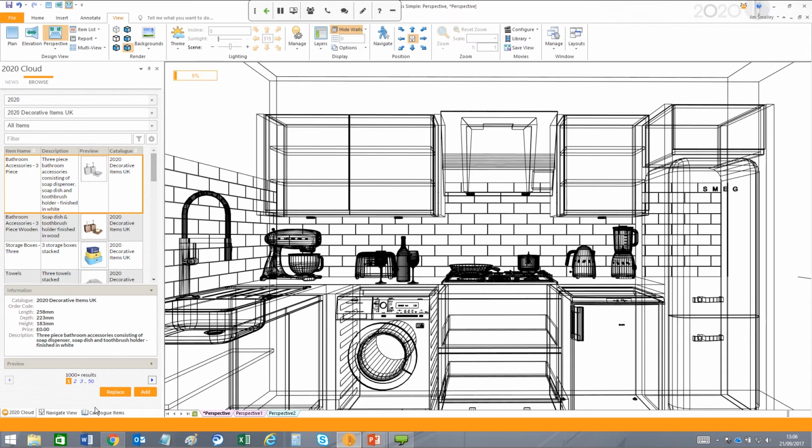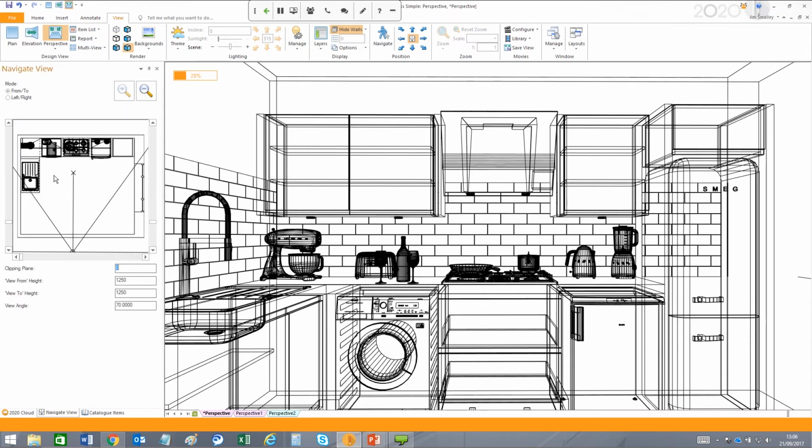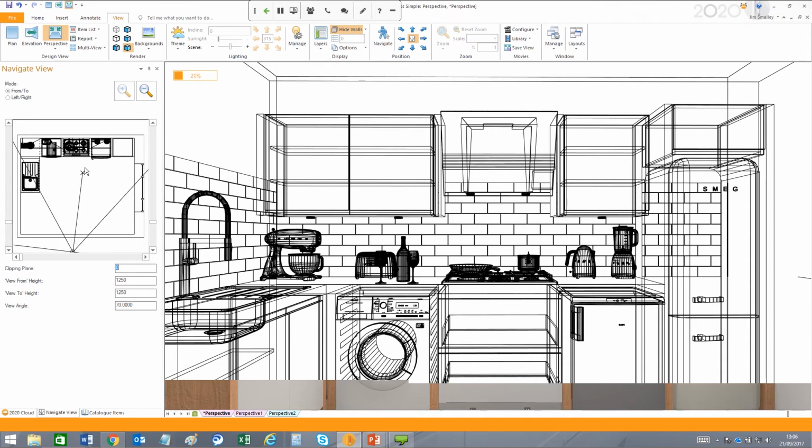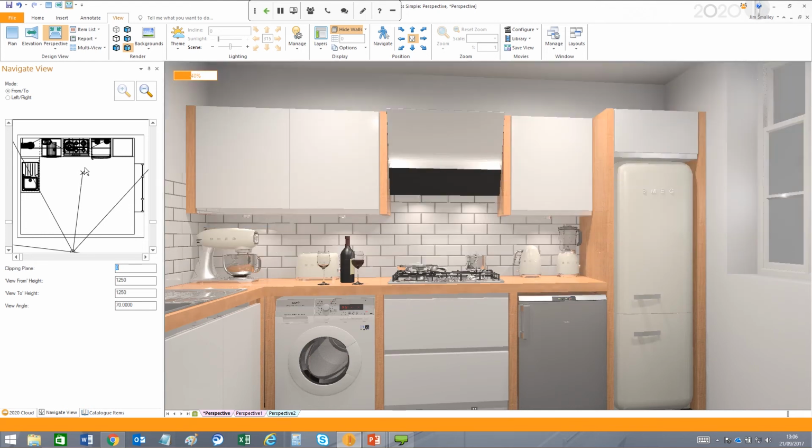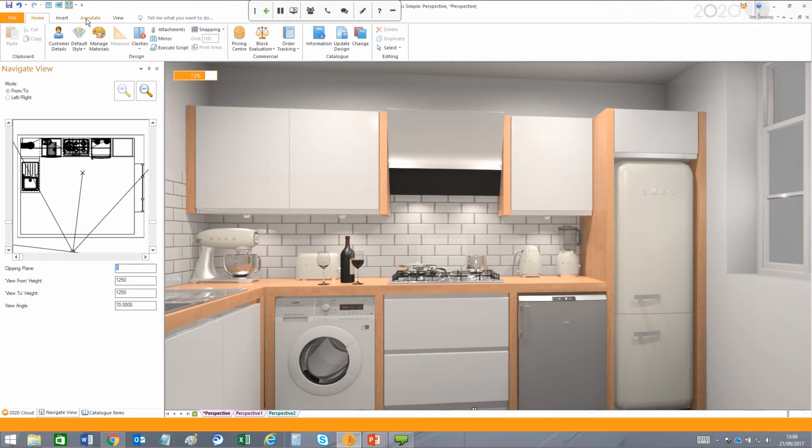And if, for example, from your navigate point of view, maybe you don't have the view quite correct, and you wish to reposition, then it will reset the rendering instantly. There's no need for you to intervene by cancelling or reselecting another render. Once the render is complete, then you are free to choose other renders, of course, but even in the meantime, whilst waiting for that render to complete, you are able to prepare your next move. Again, in Fusion, previously you were not able to even select other options whilst the render is taking place.